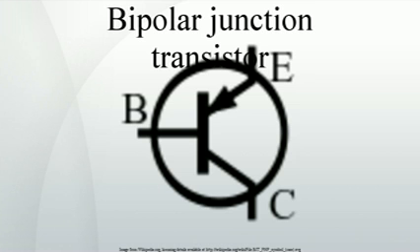Heterojunction bipolar transistor. The heterojunction bipolar transistor, HBT, is an improvement of the BJT that can handle signals of very high frequencies, up to several hundred GHz. It is common in modern ultrafast circuits, mostly RF systems. Heterojunction transistors have different semiconductors for the elements of the transistor. Usually the emitter is composed of a larger band gap material than the base.